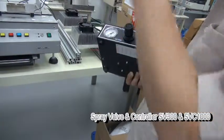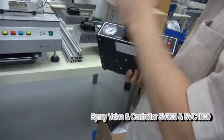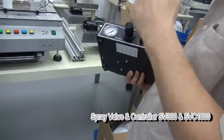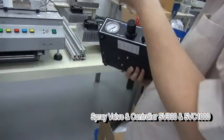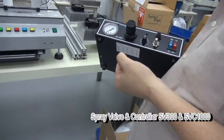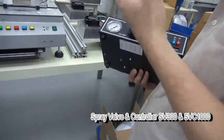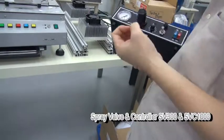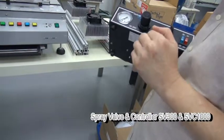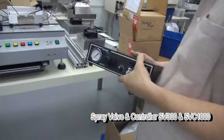After we pressurize the syringe, and then when we stop, we cut off the air, right? Then this will kick in. This is a vacuum. It will create a vacuum to pull back the material. You are continuously pulling at a constant vacuum? Depends on the timing. If the time is long enough, the vacuum can be constant. But if the time is very short, then it has no time to reach the set value. It all depends on how the customer sets it.